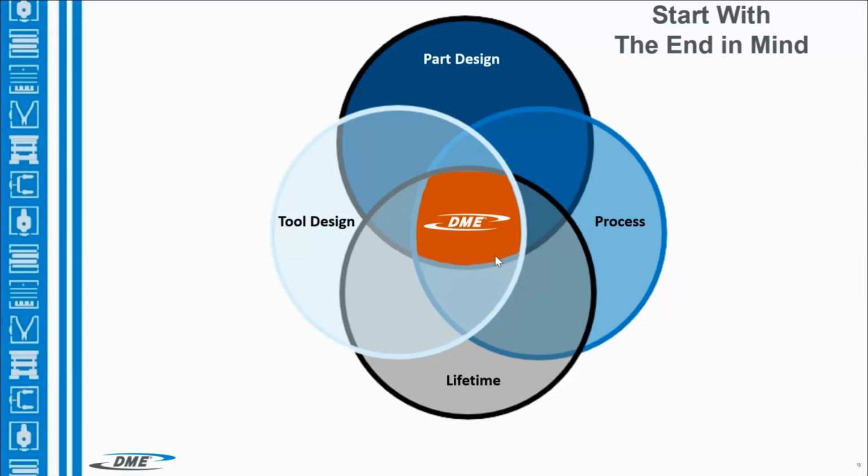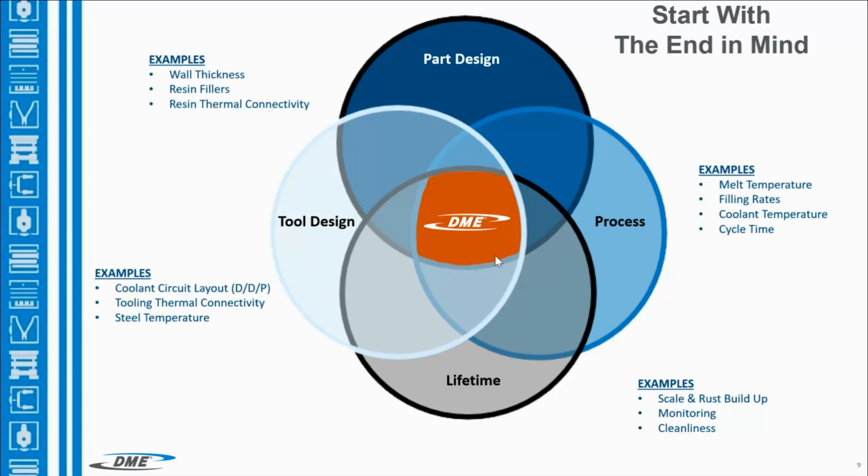So some of the things that we typically fight on a molding side from thermal management is wall thickness. It's a big deal. If you designed that in your part and you tossed it over to the molder and said, make me a part, if it's non-uniform wall thickness, we have a hard time making good parts all the time. Same thing with fillers or exotic materials.